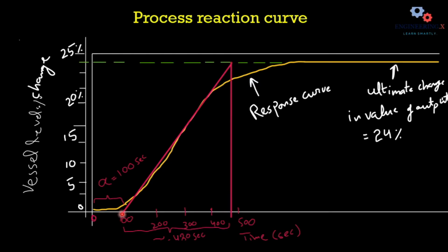The time from where this tangent line crosses the x-axis until the point where the vertical line crosses the x-axis again is called the time constant, tau, that is required to change almost 63.2% of the total response of the system.